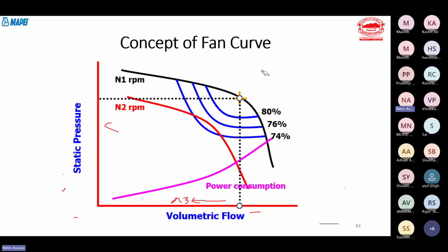Suppose you're running the coal clinker mill and your DP is on the higher side at 86% RPM. When the DP is higher, we have to increase the fan RPM to maintain the same dust loading. Because if you increase the DP, automatically my system resistance will increase.